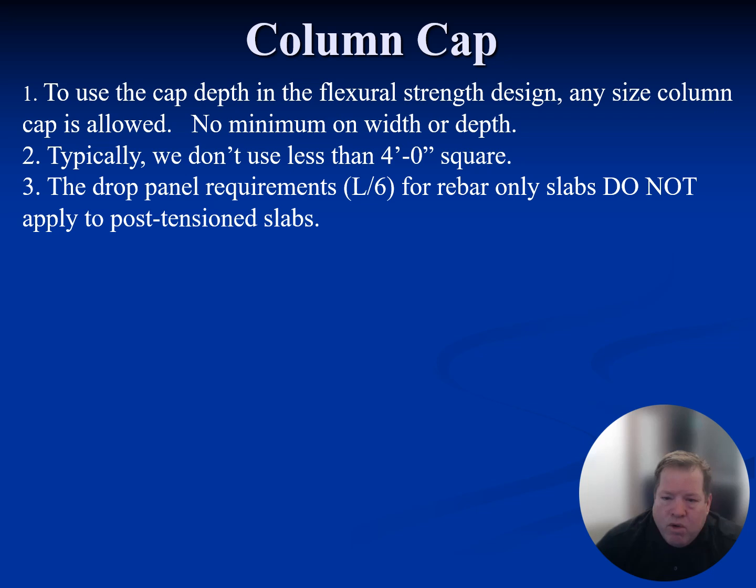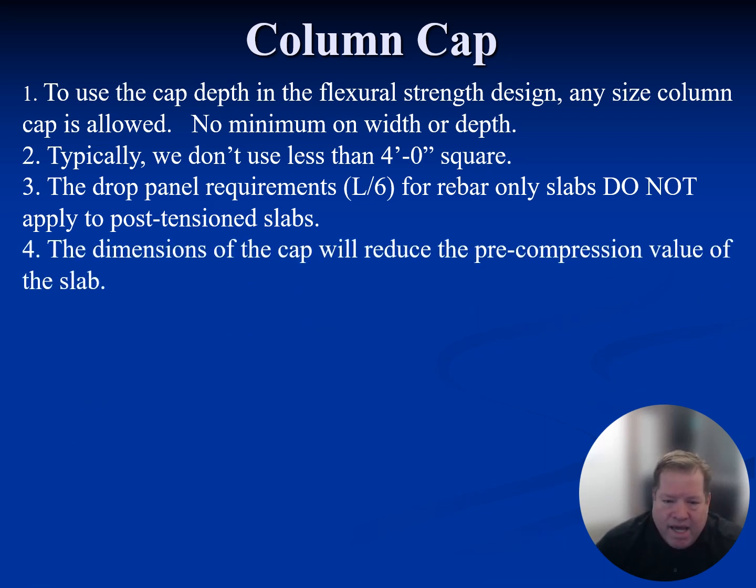The drop panel requirements do not apply to post-tension slabs. That is a rebar only system. You can use a 5 foot square cap, an 8 foot square cap. You have the same abilities. Whatever you want to do, it's engineering judgment. But again, the L/6 requirements do not apply to PT slabs.